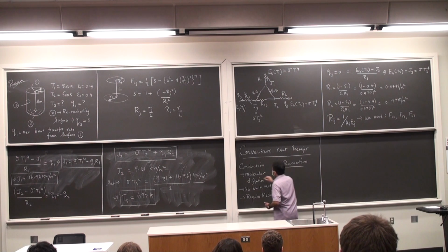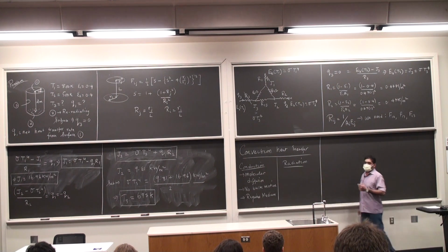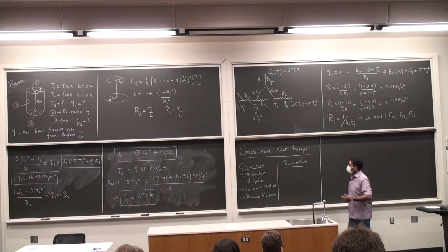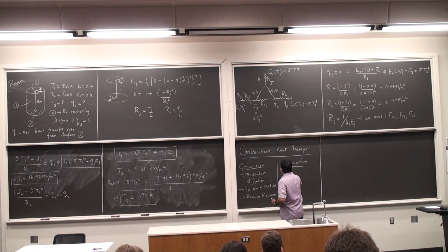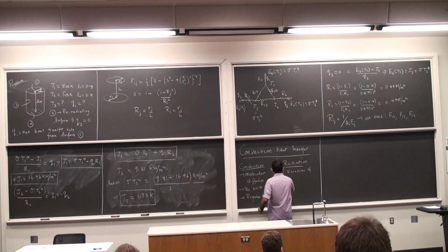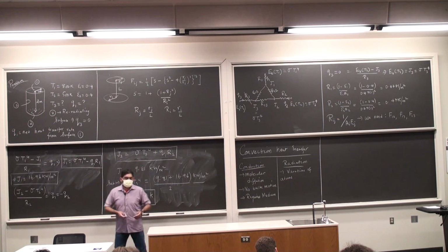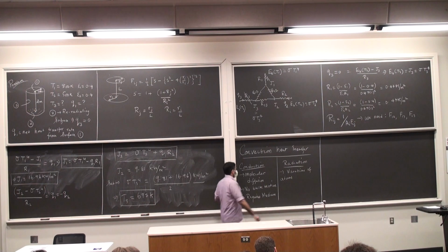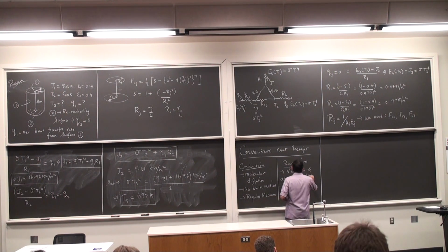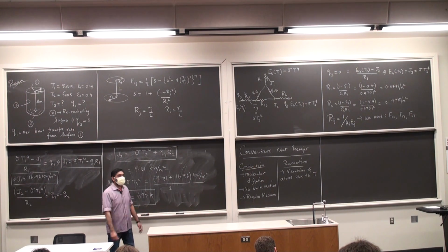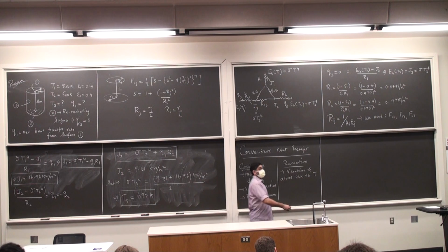Radiation heat transfer is much more physics based in some sense. This is going to take place as a consequence of the temperature of the body, due to vibrations of the atoms as a consequence of the internal energy of the body, or due to temperature, capital T. There is no need for any medium present for radiation. It's best if there is no medium at all.